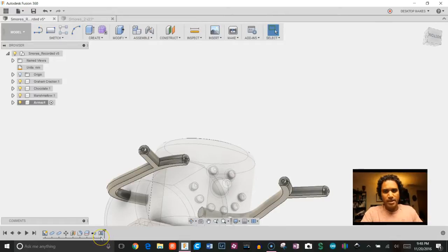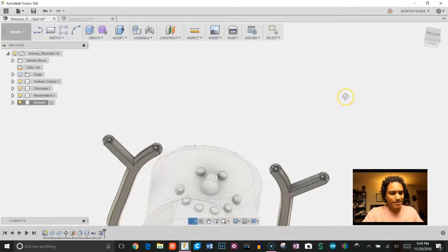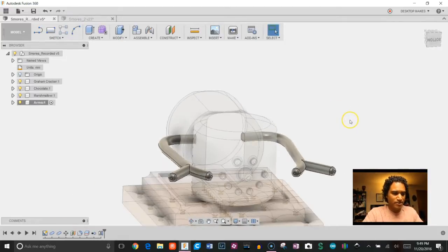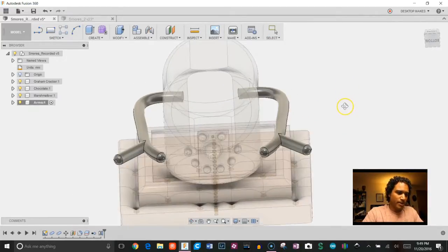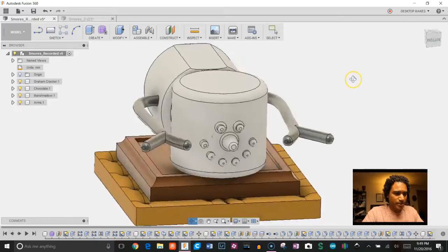And that's what's beautiful about having a timeline feature here and having a parametric drawing or modeling software, is that we can just move that timeline back, say, oh, you know what, I should have done the fillet here. Just go ahead and pretty much go back in time and do that, and then go back to the future, and it carries everything forward. So love that about Fusion 360. Okay, let's see how everything looks. So we're going to go back, activate the top of our component here.